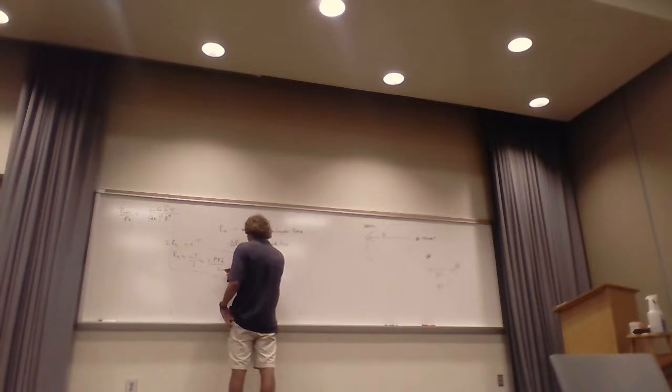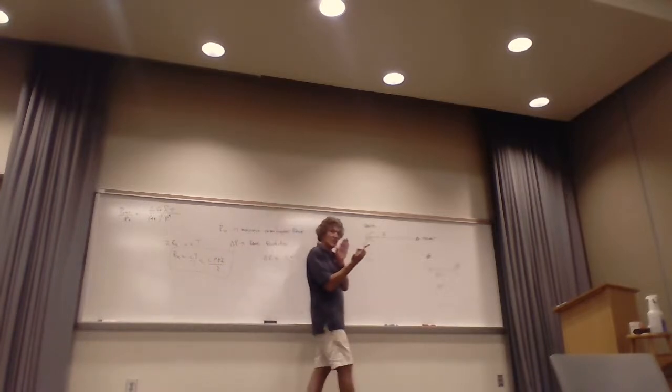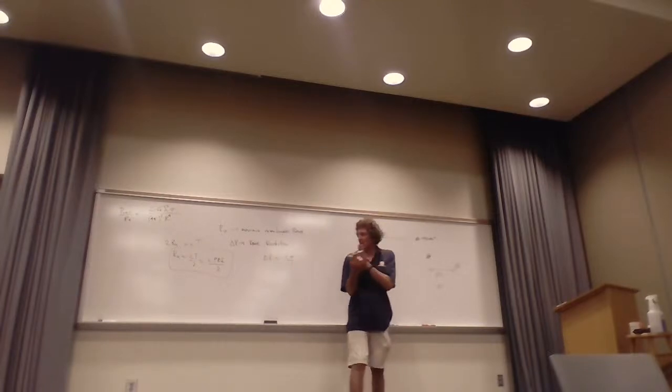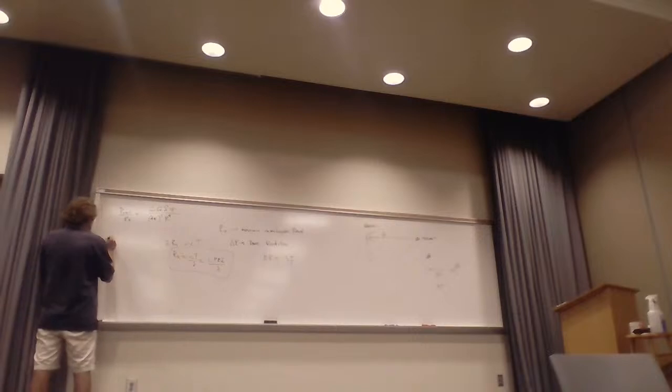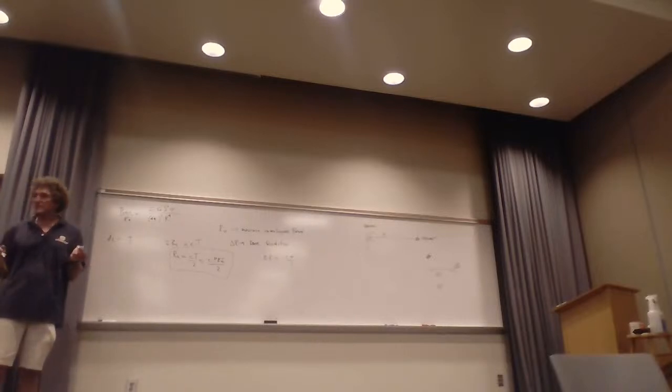It's going to be the same form as that, only it's C tau over 2. And the reason it is tau is just the on time. And the duty cycle, I didn't put this down, but I assume you know this. When you talk about the duty cycle, that's simply tau over T. It's the percentage of time the thing's on. Typical duty cycles are between 10 and about 30%.